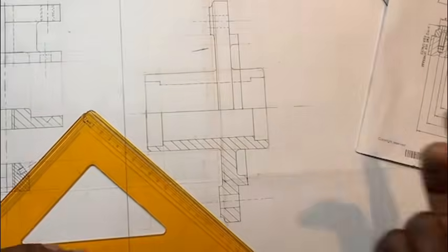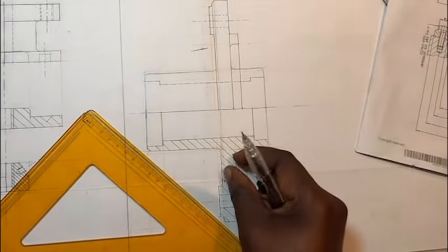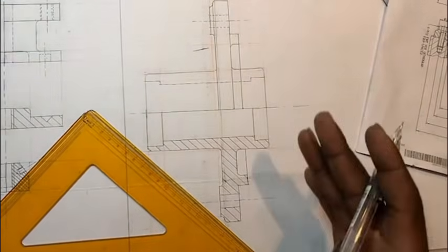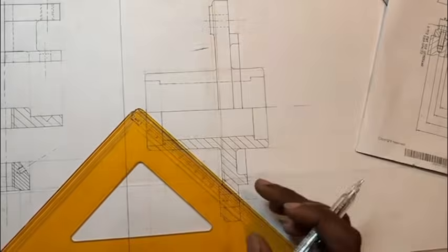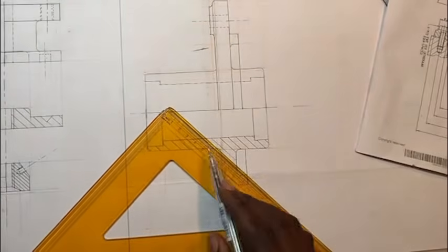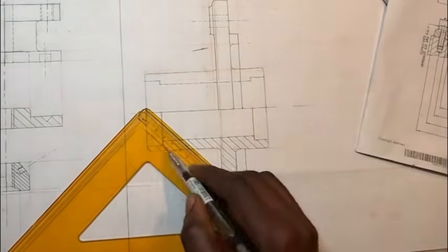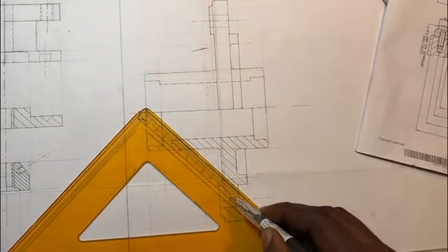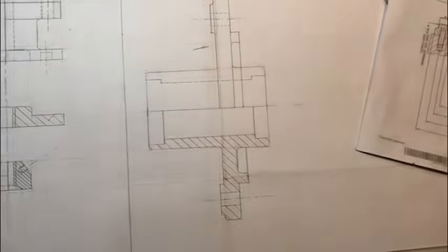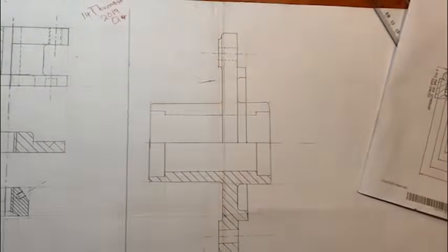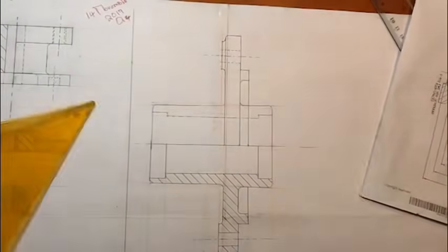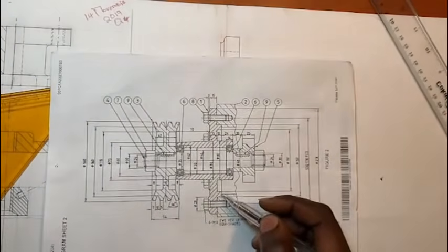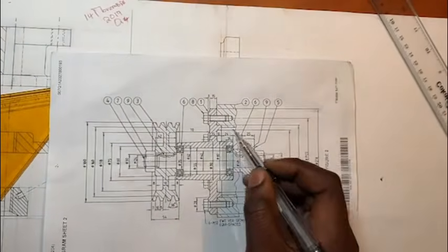So to answer your question, you are not restricted to how far away they are supposed to be spaced from each other, as long as they're at an angle of 45 degrees, equally spaced. You can mark your 45 degrees using this marker, so that you know these are your spacers for the sectional drawing. The upper part is supposed to remain as an outside front view of item 1. So what is left there now, my brother, is this one.